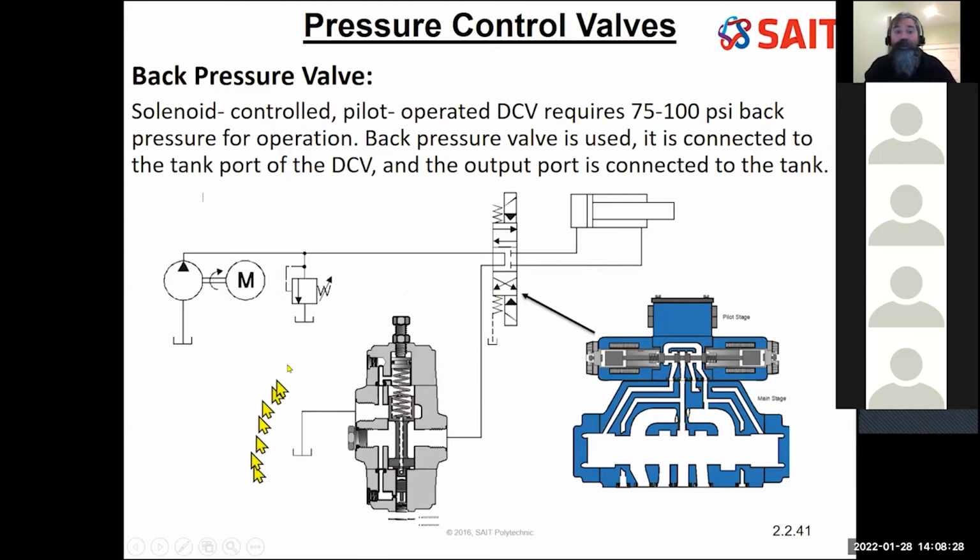So I want to create this back pressure valve to create some back pressure. The other place I might want to use this is if I am creating a rotary system. I don't want it to freewheel on its own. I may want a little back pressure so that someone walking past it or vibrations are not going to make this rotate unless it's under control. So a back pressure valve is desirable to gain better control of my circuitry.